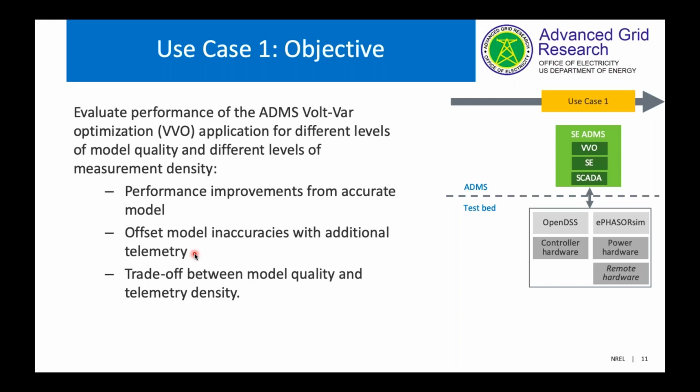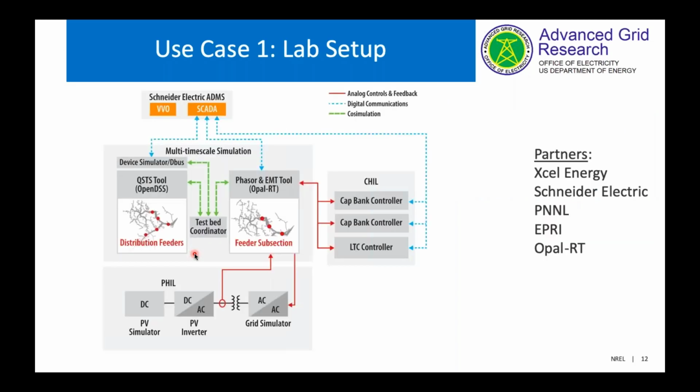On the test bed, we selected a subset of those combinations to simulate. And this is the specific setup that we used in our laboratory. As you can see, just a more specific version of the generic diagram that I showed earlier. So we have our Schneider Electric ADMS with the VVO application, our OpenDSS and ePHASORSIM combined simulation.